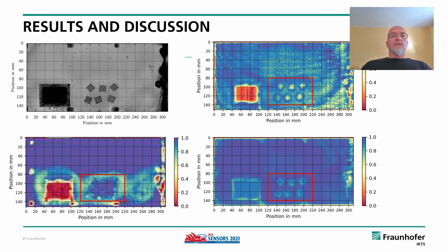We can see on this slide on the top left the reference true transmission C-scan. Bottom left is the normal pulse echo C-scan with usual post-processing to reduce signal fluctuation, such as cut-in time, root mean square averaging. Because of the signal fluctuation, some defects are not detectable at all and are marked with a red rectangle. On the right side are the visualization of the pseudo-probabilities obtained with autoencoder trained on signal, right top, and the PFA, right bottom features. The brighter spectral colors indicate a higher probability of anomaly or defect.